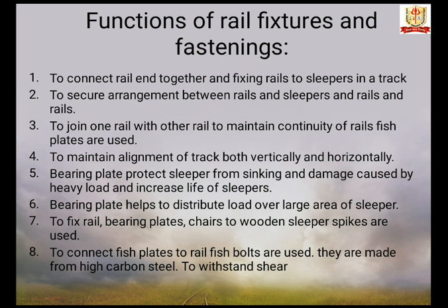Bearing plates protect the sleeper from sinking and damage caused by heavy loads and increase the life of the sleeper. Bearing plates help to distribute load over a large area of the sleeper. To fix rail, bearing plates and chairs to wooden sleepers, spikes are used. To connect fish plates to rail, fish bolts are used. They are made from high carbon steel to withstand shear resistance.